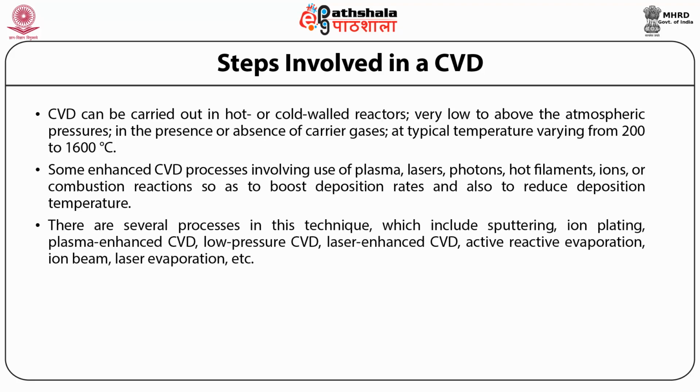There are several processes in this technique, which include sputtering, ion plating, plasma enhanced CVD, low pressure CVD, laser enhanced CVD, active reaction evaporation, ion beam, laser evaporation, etc. All of them differ in the manner the chemical reactions are initiated and can be distinguished by their working pressure range as follows.